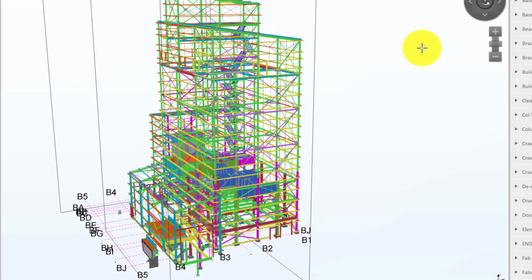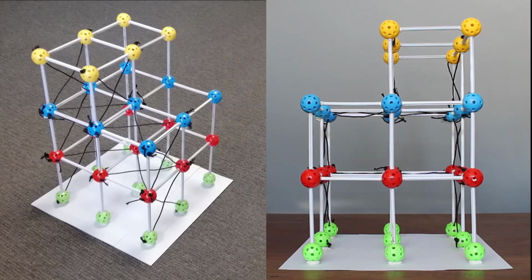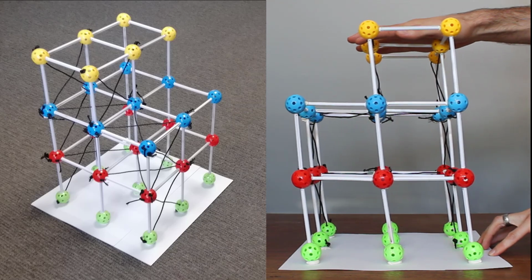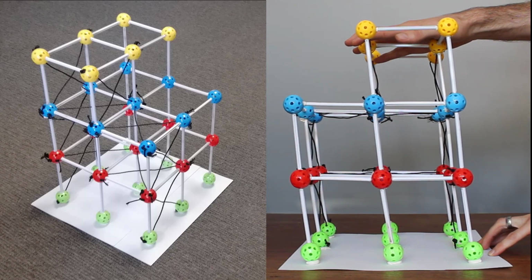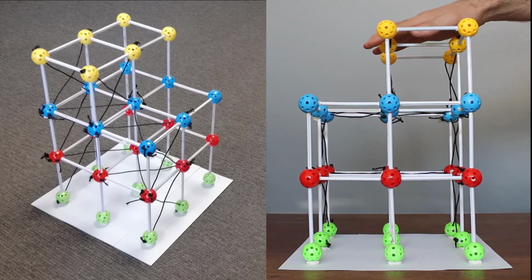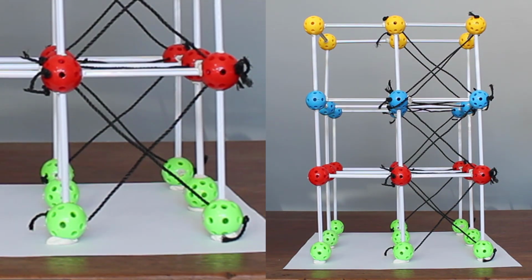So hopefully that's given you a bit of an overview of practical bracing, and now we're going to go back to our very, very simplified layout to try put this into practice. Here is a model of the structure, and if we load it in the direction in which it's not braced, we actually have a mechanism, and if these were true pins, the structure would fall down.